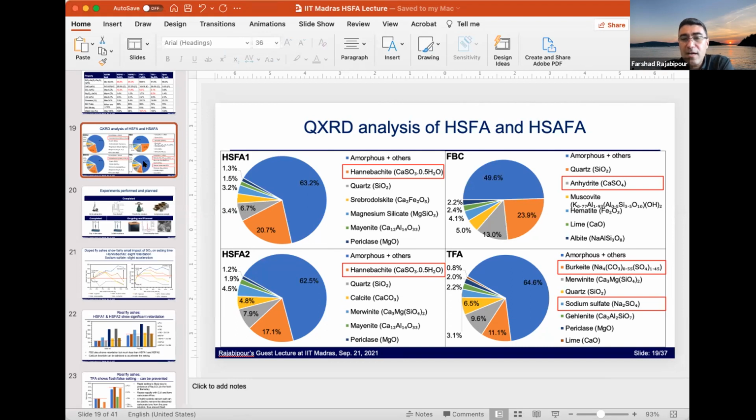So they usually end up overdosing the Trona when they are doing their scrubbing, and some of the sodium carbonate or alkali carbonate may remain unreacted in the fly ash. Essentially, you run out of the sulfur, and then everything else is going to be sodium carbonate.